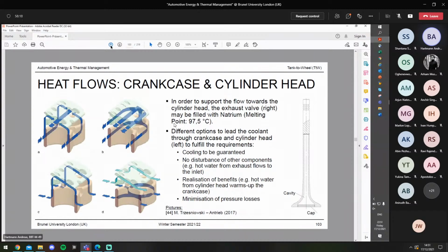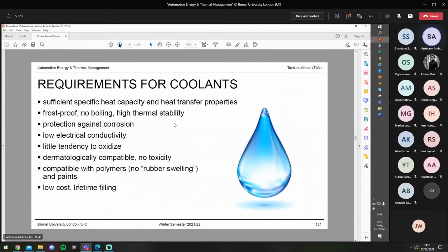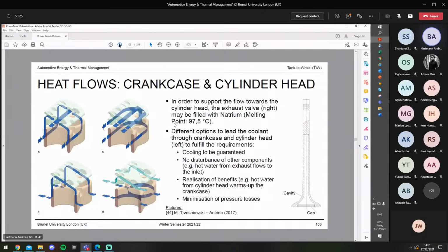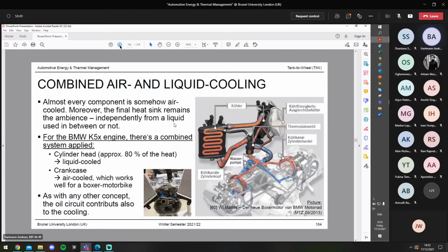And for this, actually the same rule as just mentioned for the radiators applies, means the coolant first needs to pass by cooler parts of the engine before it reaches the hot regions. In order to not heat the one with the other, this should then be the right sequence to apply.